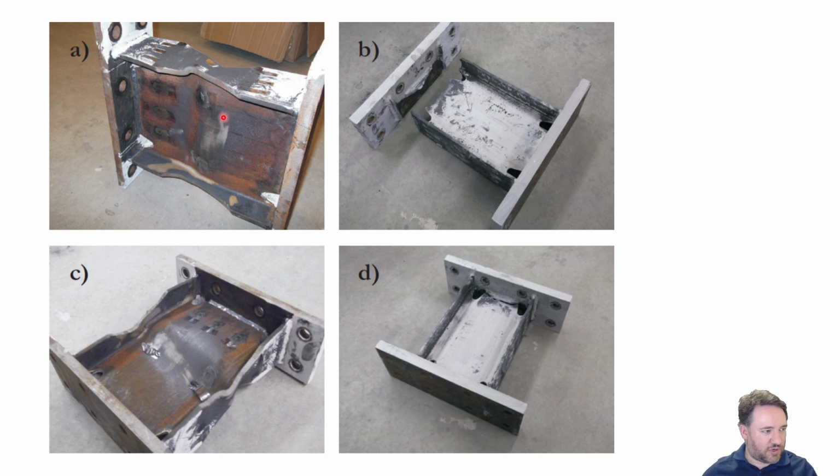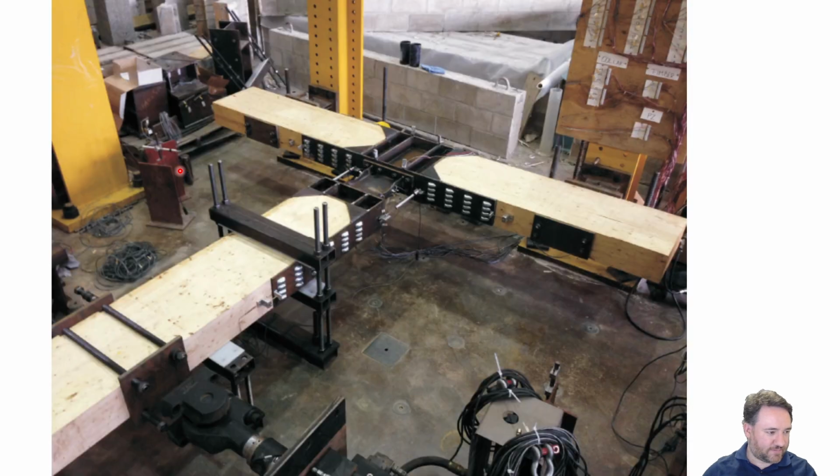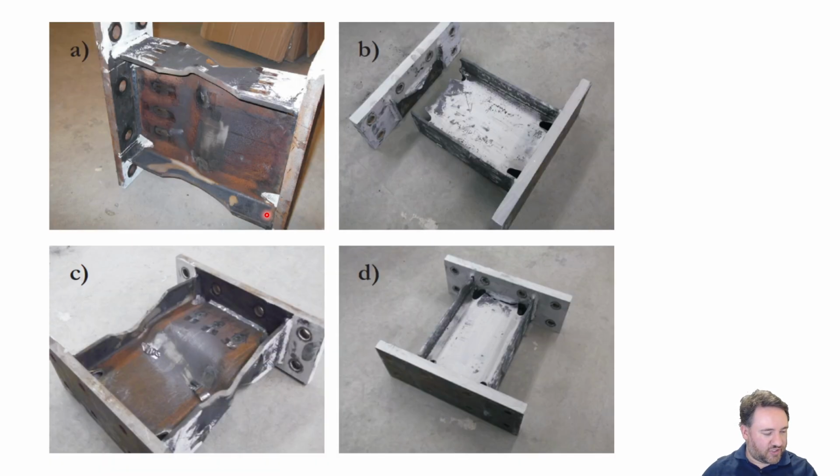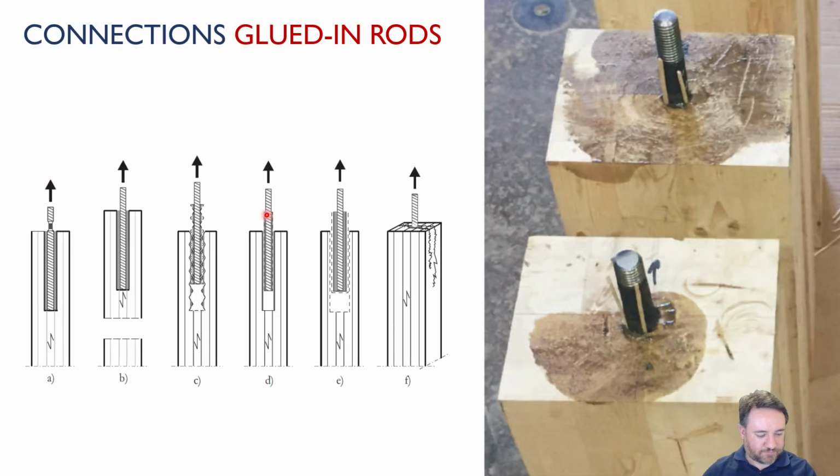We can totally destroy this pretty big sizable steel connection using wood members to provide the load. So here, the load is applied out here directly to the wood, and the resistance is out here applied directly to the wood. So basically the wood member is yielding the steel member, and the wood member remains undamaged. That was kind of the goal of our research study.